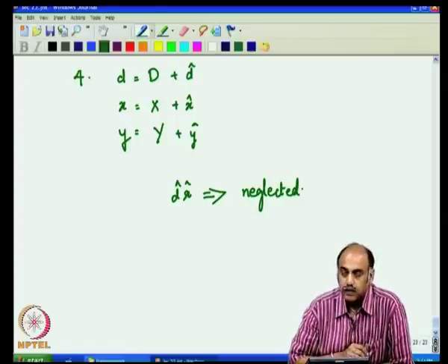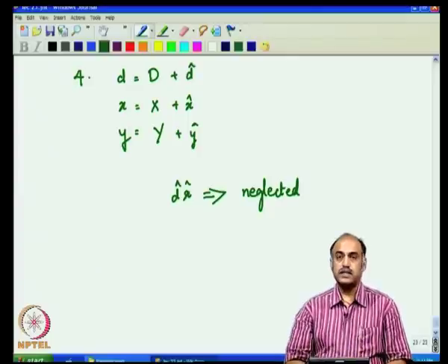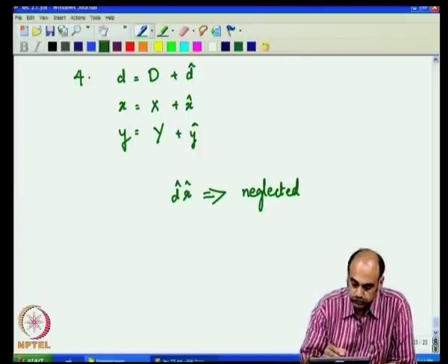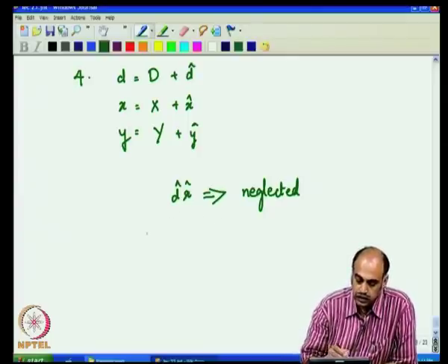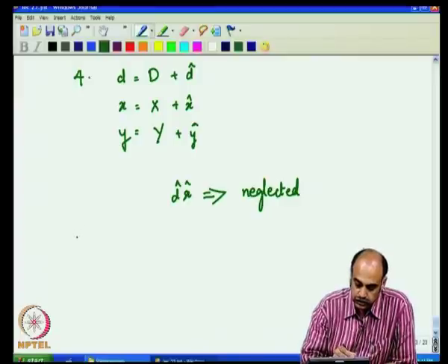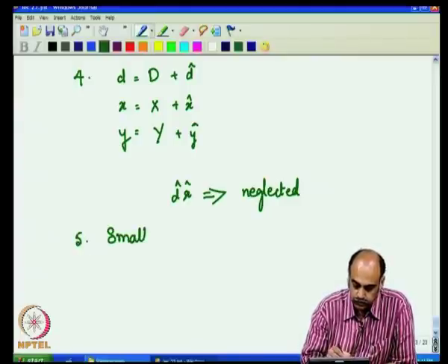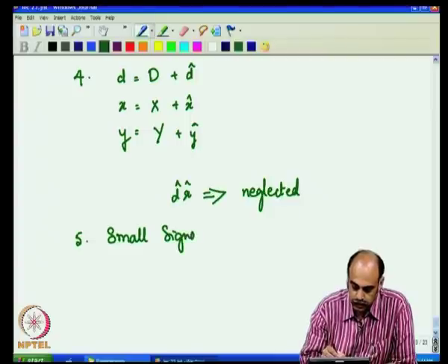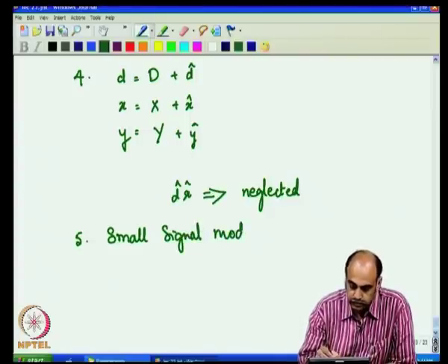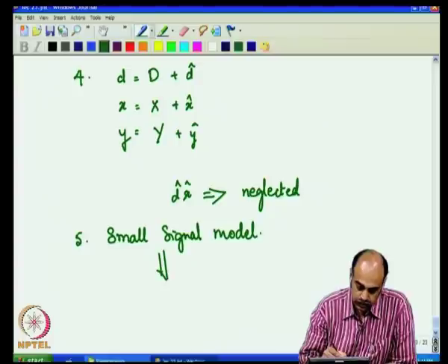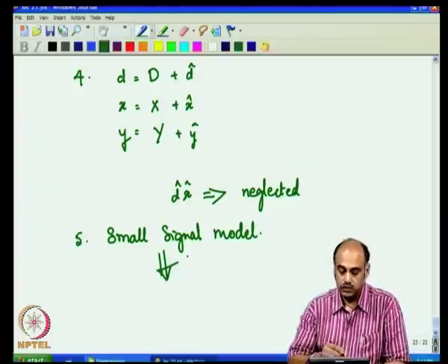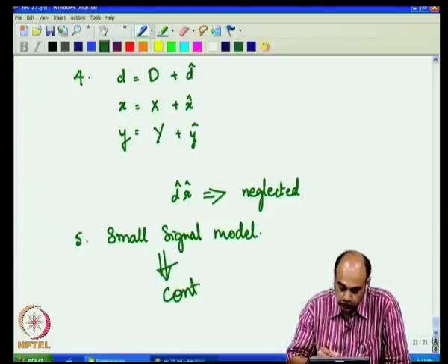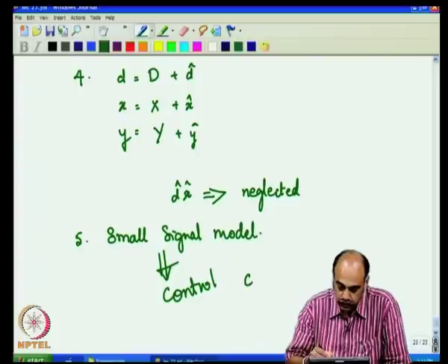Take only the first order small signal products and you will end up with the small signal model. And this small signal model has to be used for your control or controller design.